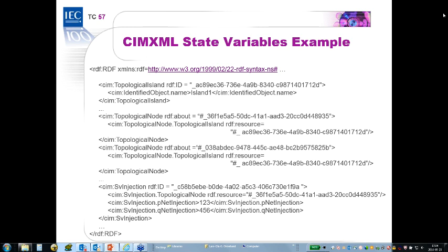So, an assembly procedure selects the model parts, makes the necessary updates to model parts, for example, to go forward in time, sets up a steady state hypothesis, executes topology and power flow to produce a base case, validates as necessary, and then exports to your favorite set of planning study tools where you run as many different variations on that original base case as you need to do.